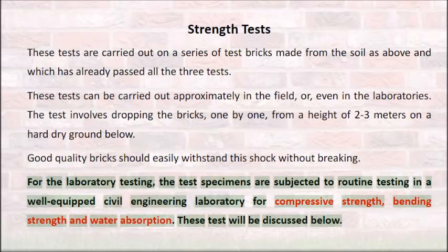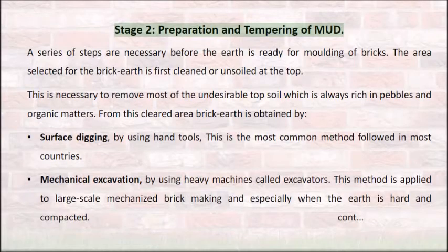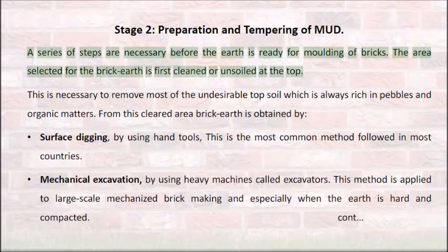For the laboratory testing, the test specimens are subjected to routine testing in a well-equipped civil engineering laboratory for compressive strength, bending strength, and water absorption. These tests will be discussed below. Stage 2. Preparation and tempering of mud. A series of steps are necessary before the earth is ready for molding of bricks.